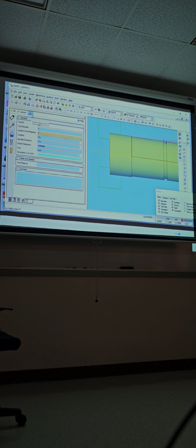We don't need a center drill first? Not on this one, you can, just to speed it up, but if you know how to do a drill, just like in the mill, right? So you know how to do a center drill, tap, or whatever. But like in real life, if we're on the machine, it depends. If you're doing aluminum or that plastic that is outside, you don't need a center drill, right? Now, it depends on the material. If you're doing some exotic metal, so yes, you need to use a center drill for guidance.